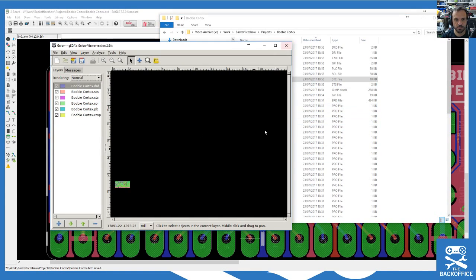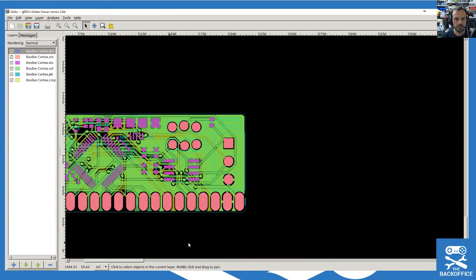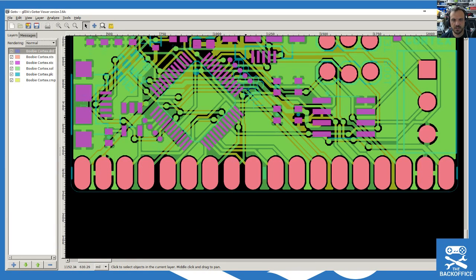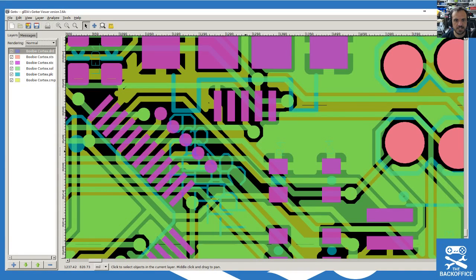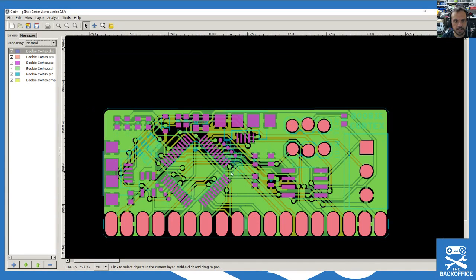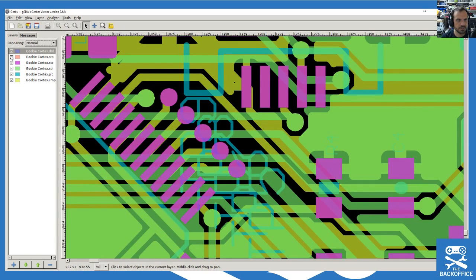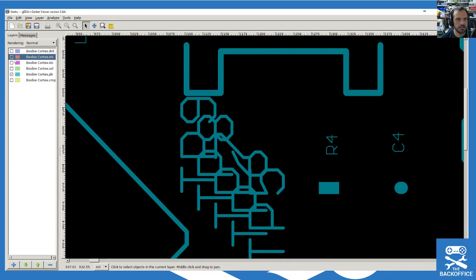Right, not all of them will open, of course, because some of them are drill files and stuff. Look at that. Now, it's really weird. Sometimes there are errors that will just make it through the whole rest of the process until you get to the Gerber, and then you'll see it and you'll really get annoyed. So here's something weird. You can see there's a load of these numbers going in. What layer is that? This PLC layer.